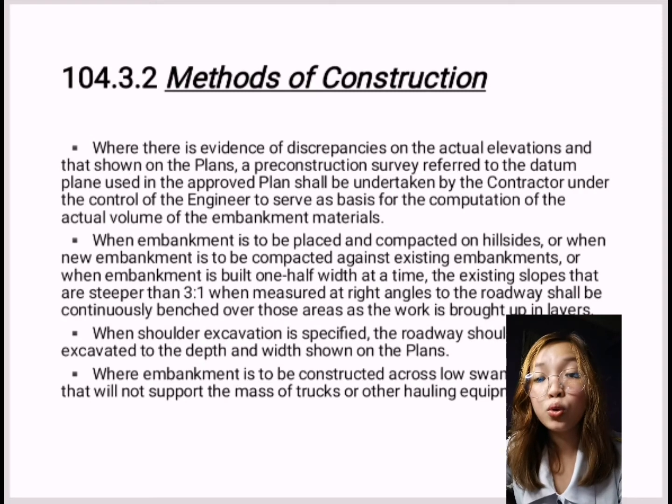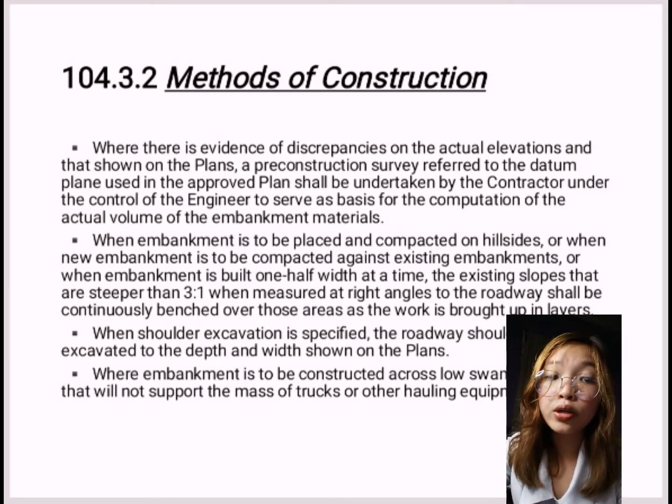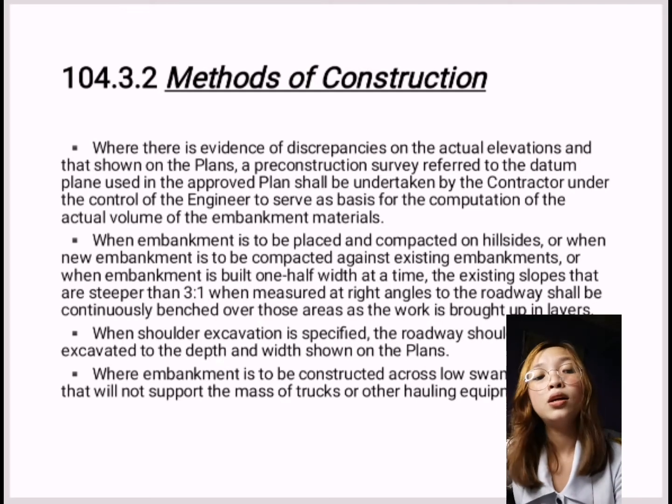So next is when shoulder excavation is specified. The roadway shoulder shall be excavated to the depth and width shown on the plan. So the shoulder material shall be removed without disturbing the adjacent existing base course material.